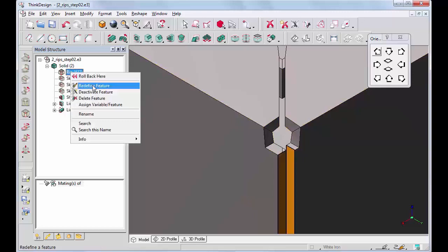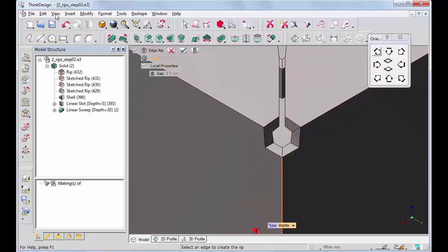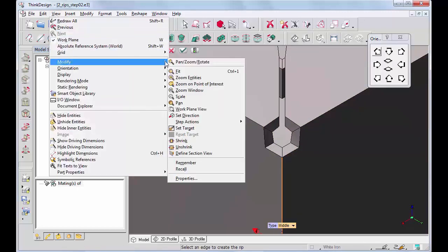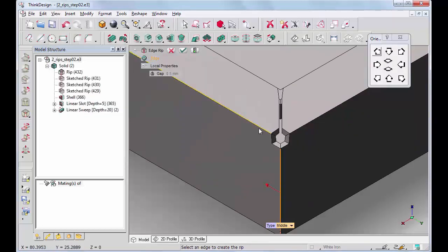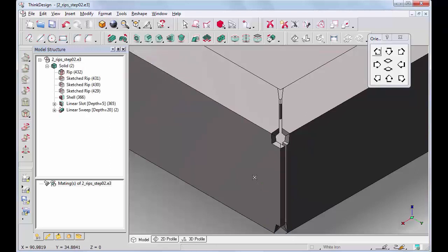In such a case, the 2 adjacent parts are cut along one of the 2 common faces. We are now setting the view properly. Also, in this case, you can choose which one by double-clicking on the arrow, identifying the cut direction. And the rip is aligned along the edge identified by the selected direction. In our specific case, we shall invert the cut direction by double-clicking the arrow, and will eventually obtain that the identified part will fully overlap with the other one.